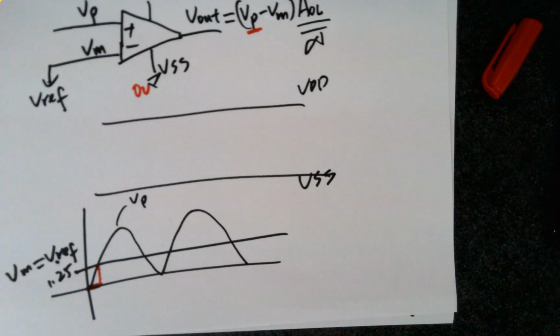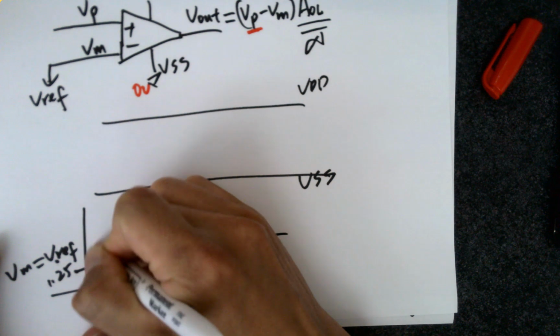It's so strong, it just wants to pull it up so quickly. But is it infinite? No. Definitely it's charging up the caps. It's charging up all the parasitic capacitance in the circuit. It takes a finite amount of time. So it's going to rise to where?